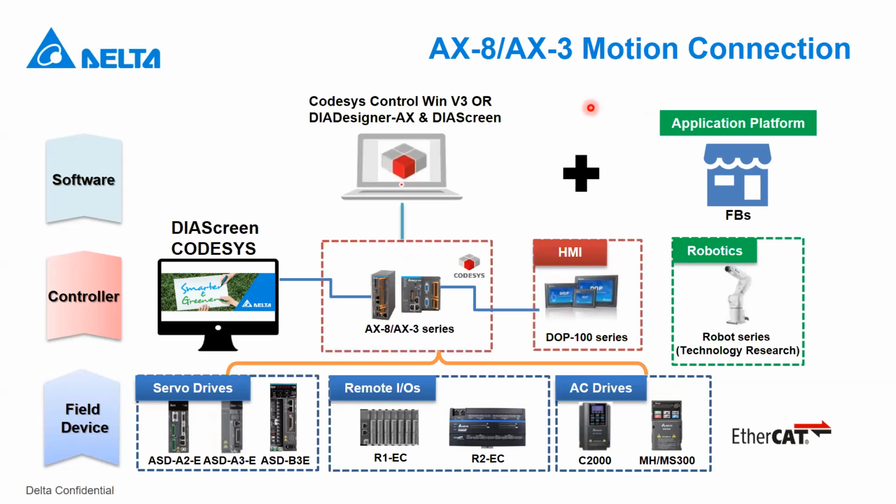And this page will show you AX3 and AX8 connection. So here you can see we'll use CODESYS platform or DIADesigner AX. Then again, PC based, you can use either monitor or HMI, but PLC based, you can use only HMI. And for the field device is the same.